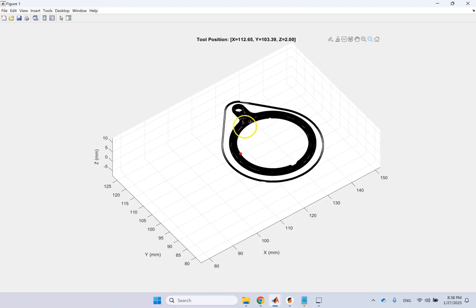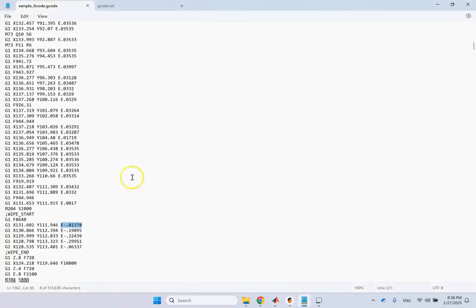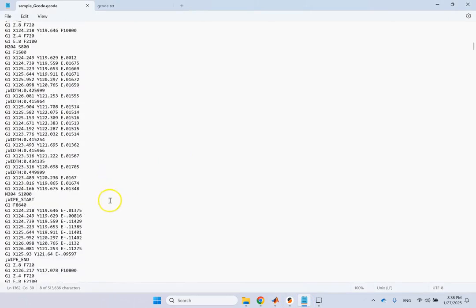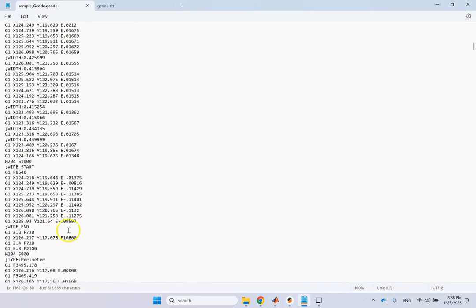The reason is when it goes from this side to this and it wants to start the next layer, it retracts the plastic, the filament between them, and you should not animate that. So you should exclude negative E lines from your basically G code, okay? And I did not initially do that, but after I looked at the animation, I found out.